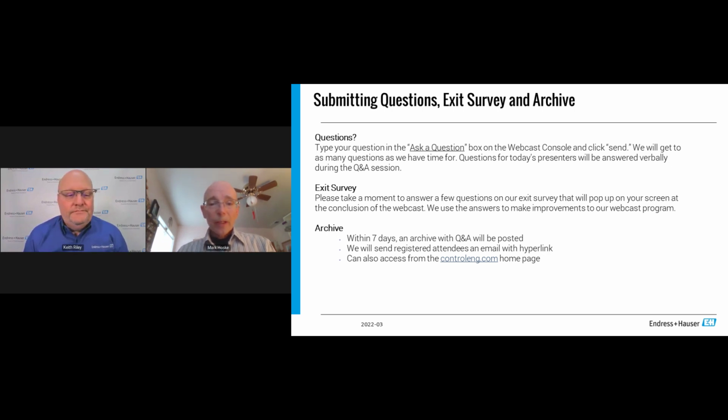Good. Let's see. Where do the heartbeat messages go? To an Endress+Hauser support center, to an application at the user site, or someplace else? No, the heartbeat is kept locally. Again, the verification you're saving on the device, or you're typically going to save it to the device you're using to communicate with so that you've got the PDF stored. Anything on monitoring, if you can set it up as part of a variable output on your HART card, that information is going to go to you so that you can see it. So it's all kept locally.